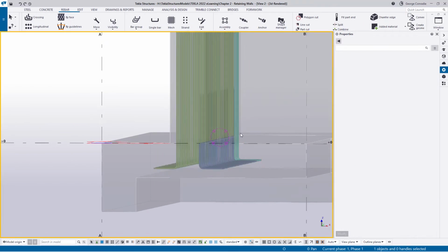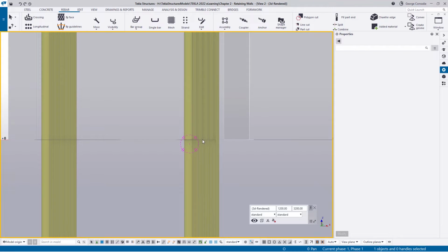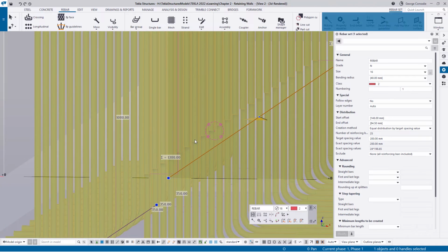But if we look at exactly where the bars are split and we look at where the concrete line is, it's exactly where the concrete will start. So just imagine they're pouring the base first and then they're pouring the wall. Normally what they'll have is a 50 millimeter kicker there. So you want that lap to at least be 50 millimeters above.